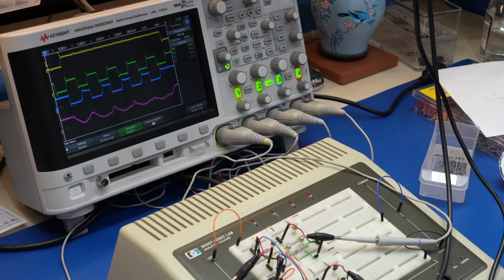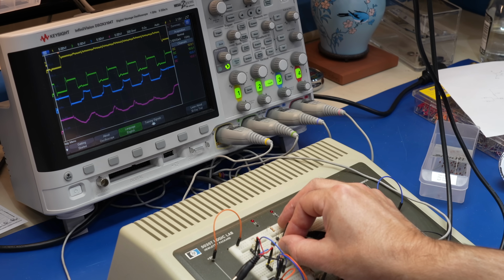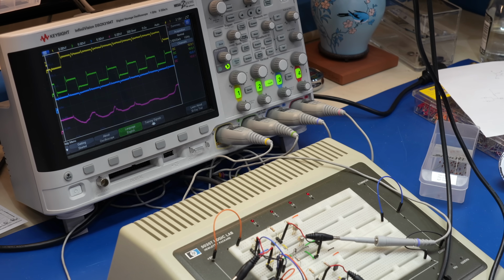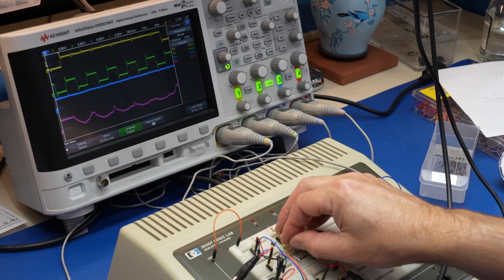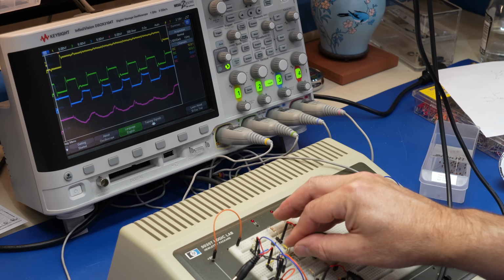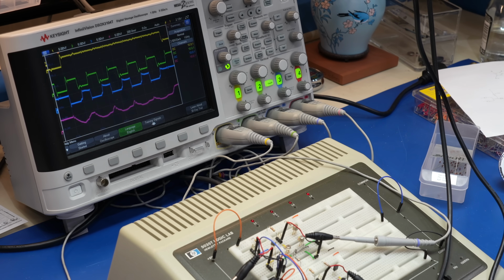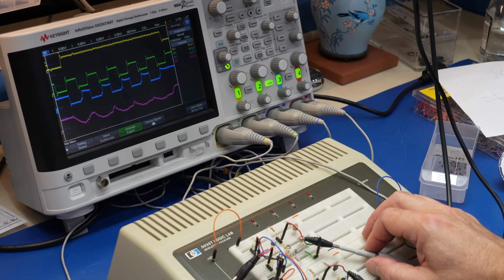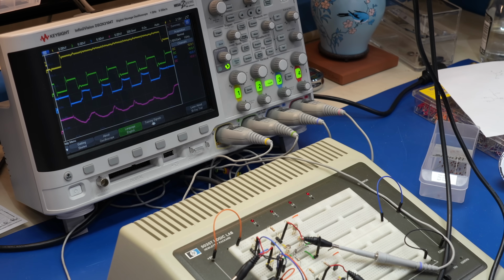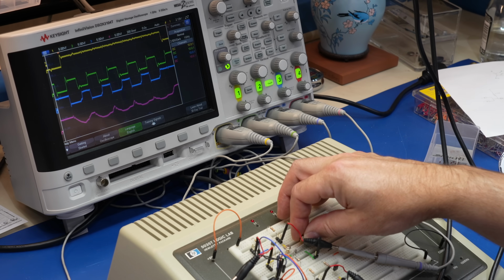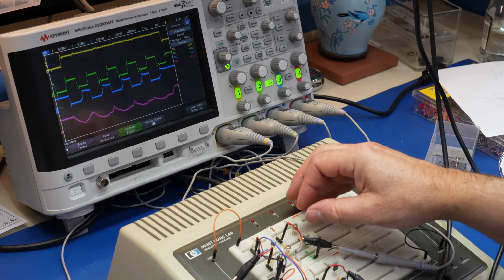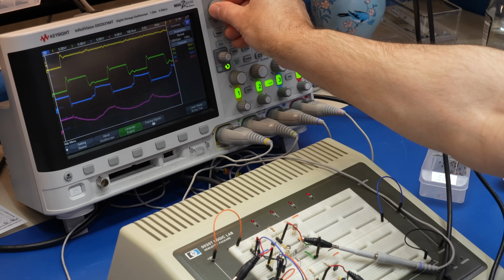For the last bit, let's put better transistors. It's a 2N2222, it's not the best, but really here what matters is how fast it goes out of saturation. So here I have an 800 megahertz transistor, but once again it's not going to make a huge difference because it's just a tiny bit faster at going out of saturation. You see that's helped already.